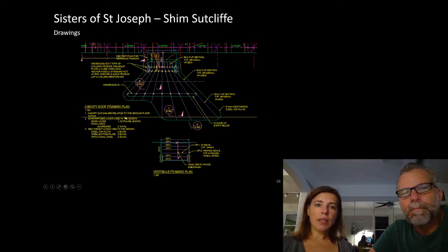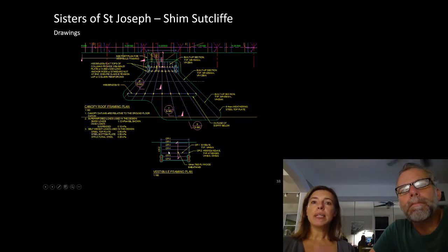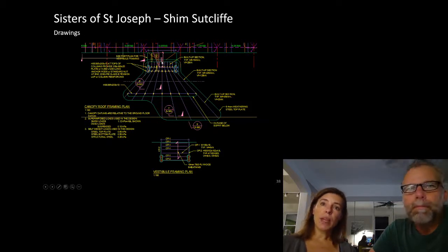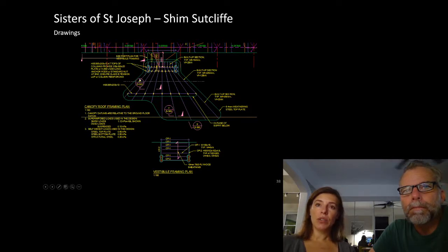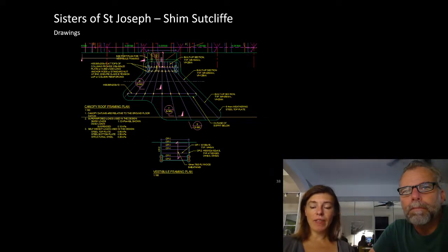Here are the loads that we used on the element. So you can see that there was top plate and bottom plate weights and our snow loads. This building was out far enough. You can see here's the accumulated snow load on the lower piece that was in between the two. So we only had accumulated snow load left back here, and this actually wasn't governed by accumulated snow load. You saw for that other project that it was 5 kPa.